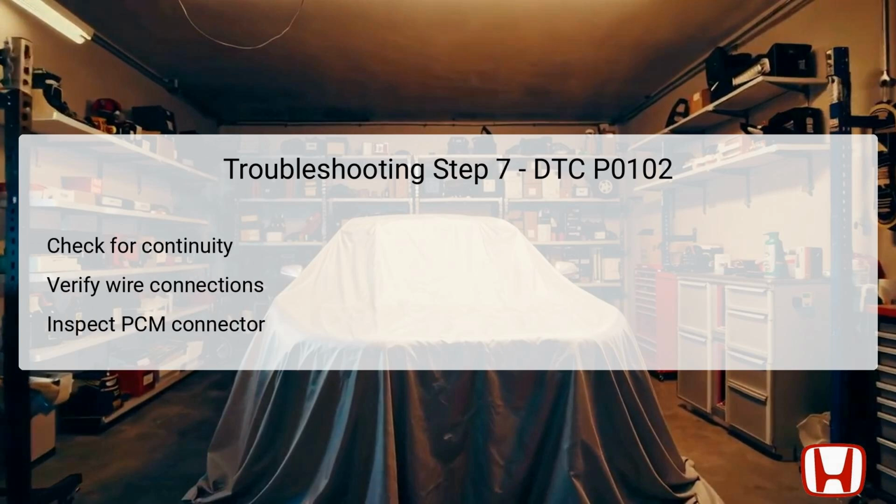The seventh troubleshooting step directs the technician to check for continuity between the specific test points in the disconnected MAF IAT sensor 5P connector and the PCM connector A. The vehicle should remain in the off mode while performing this check. If continuity is detected, this indicates that the VGP line is functioning optimally and not presenting any issues. Under these circumstances, the technician should then check for authorized service information or consider substituting with a known good PCM as the next logical step.